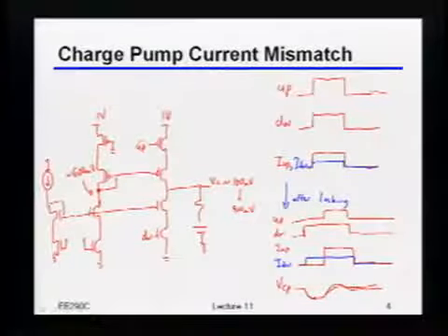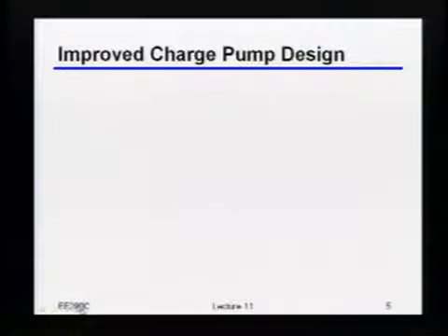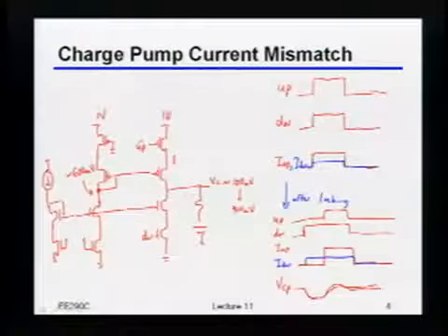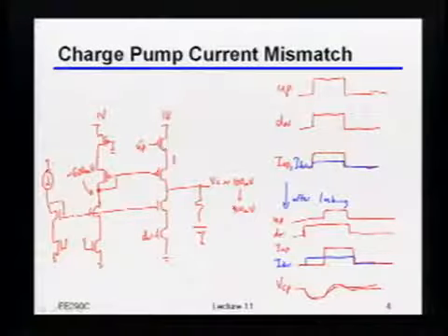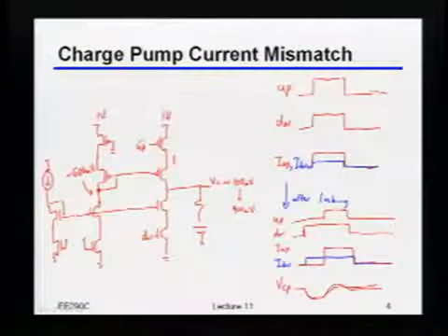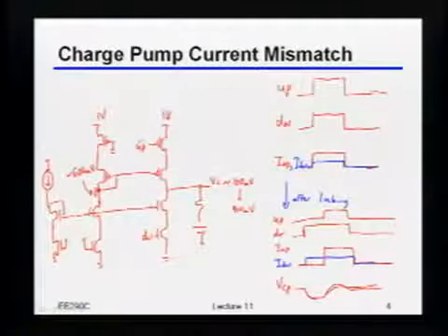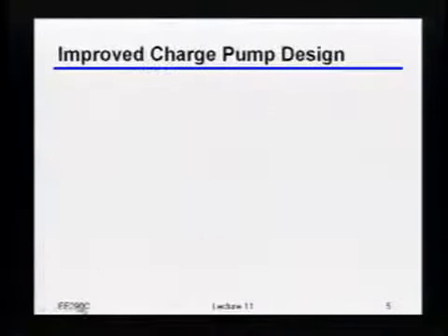Yeah, basically, right? Okay, and actually, you don't even have to be that direct. All you're really trying to do is build a better current mirror, right? So if I want the best current mirror I can get, then all I have to do is make sure that whatever voltage I have over here, I also get that voltage over here, right? And then as long as the devices match, I should indeed have a good current mirror, right? So let's just quickly sketch what that would look like, okay?